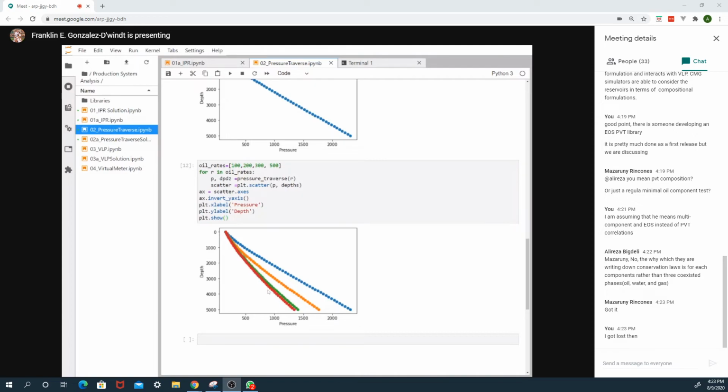So what I'm trying to say, normally what we do to estimate the rates, unless we are in a reality where we have a meter, we normally send the well to a separator and test the well for a couple of hours or a day, depending on the situation, and estimate the stabilized rate. And then we try to extrapolate what the pressures are and estimate what the conditions of the well are. But what if we have an output, I don't know, every second or every 5 seconds or every 10 minutes, at different frequencies, that we estimate the rate?